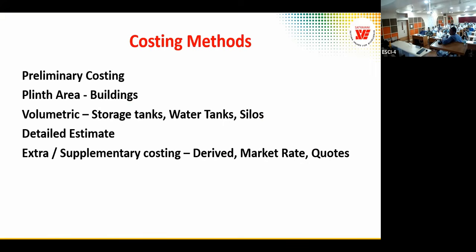So costing methods: for buildings, we use plinth area, as I mentioned, for CPWD, MES or any projects. Volumetric costing we use for storage tanks, water tanks, silos. And the detailed estimate is ultimately the next stage, after the preliminary estimate and system.